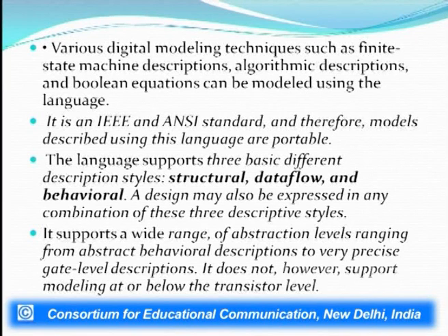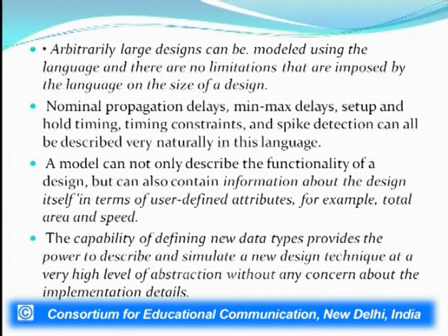Then, as I mentioned before, it supports a lot of abstraction levels ranging from the behavioral description to very precise gate level descriptions. It does not support modeling below the transistor level. That means the lowest I can begin from is the gate level and forward. Now, arbitrarily large designs can be modeled. There is no limitation to the number of gates that can be modeled. So, as big a design as is possible can be very easily written using VHDL.